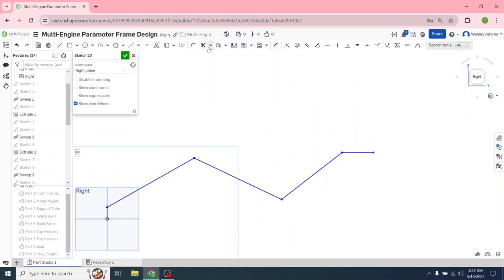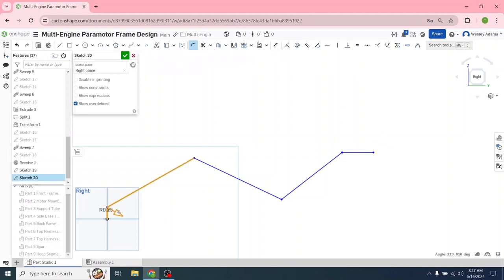Now let's go to our sketch fillet tool. Let's see if we can put a 1 inch there. We'll get a red line if it won't. All right, so good, we want that. We can change the length of this later. So this segment here and this segment, we want 1 inch. We're going to drag that down. Oops, let me double click on that so I can just hit 1 inch. I'm going to grab that so that I can see the radius of the bend there.